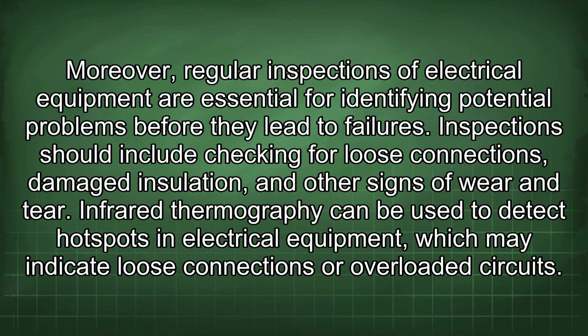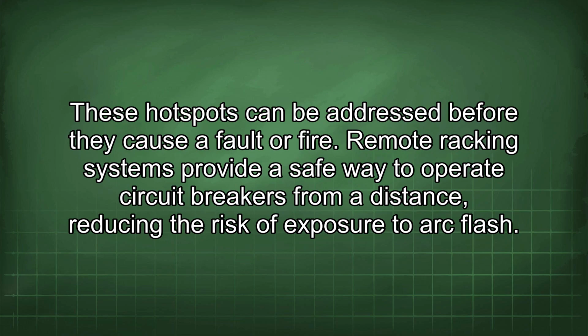Moreover, regular inspections of electrical equipment are essential for identifying potential problems before they lead to failures. Inspections should include checking for loose connections, damaged insulation, and other signs of wear and tear. Infrared thermography can be used to detect hotspots in electrical equipment, which may indicate loose connections or overloaded circuits. These hotspots can be addressed before they cause a fault or fire.